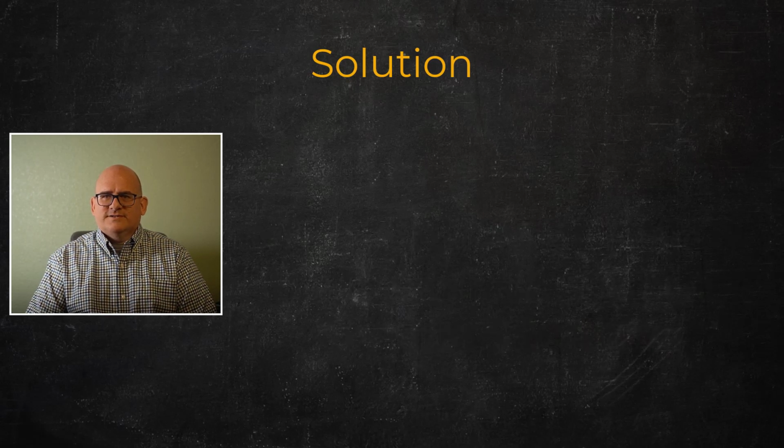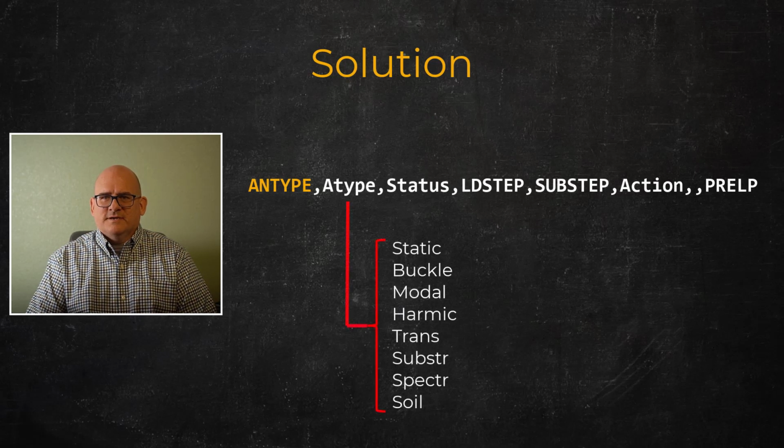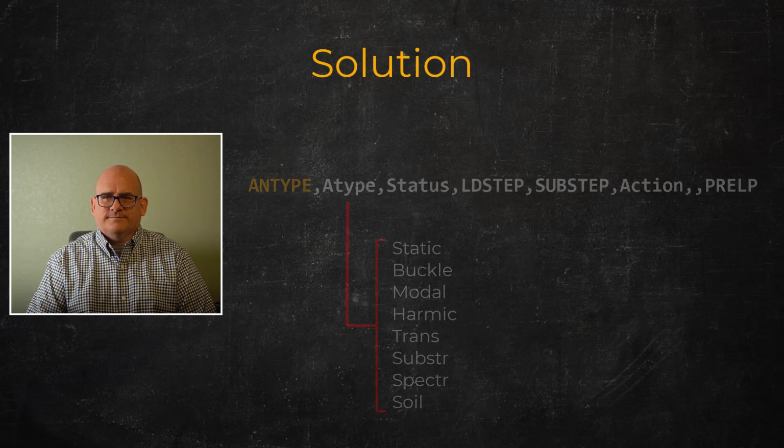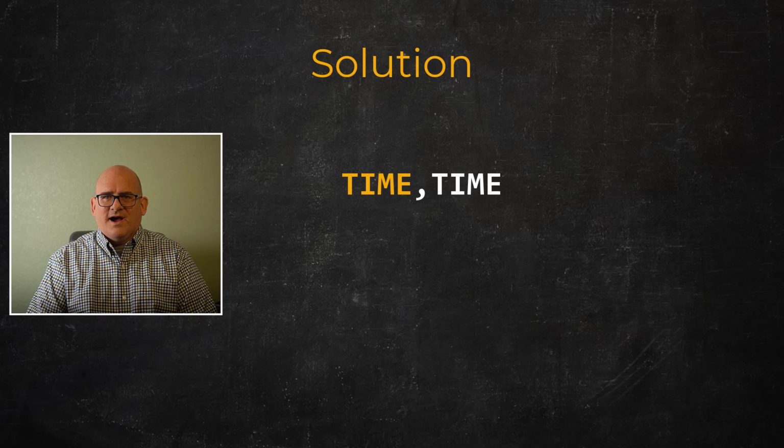Some of the often used solution commands include ANTYPE, which defines the type of solution. Static or steady-state thermal is the default. Other choices include time transient, modal, and spectrum. A load case is a set of loads defined for a specific time. The time is defined by the TIME command, with time in a static analysis acting as a counter.